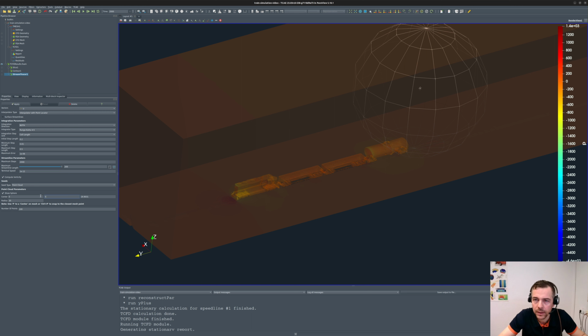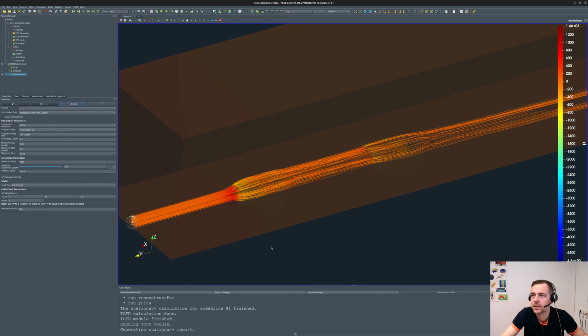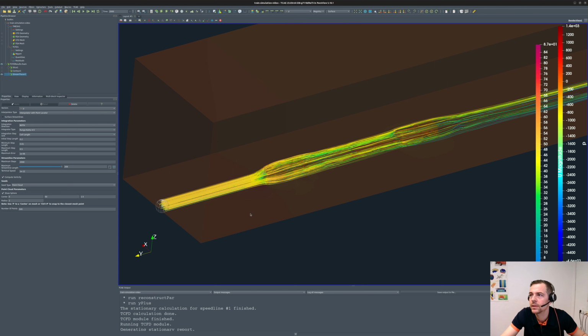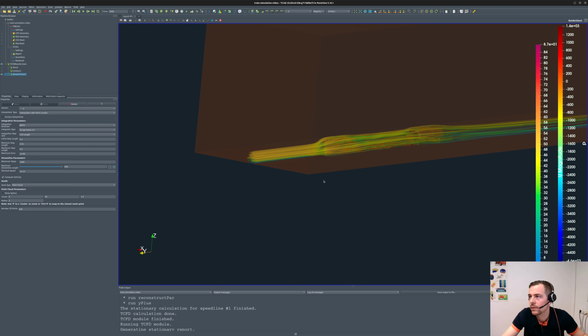somewhere in the beginning of the tunnel. So let's make it 0, 50, and the height will be not much. Let's put it to your eyesight, which is 1.5 meters, perhaps. And the size of the point cloud, let's make it 2 meters. Hopefully it works. Maybe let's make a little bit more of the number of points. Let's make 500. And these are stream traces around the model, and let's color them with the velocity field. I always like playing with display, so let's make them only like 0.2 visibility, but with more width. Let's make the width like 5, and let's render them as tubes. That's what we can live with.